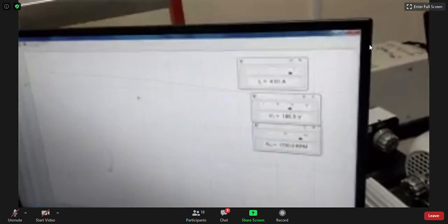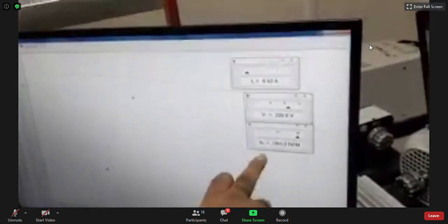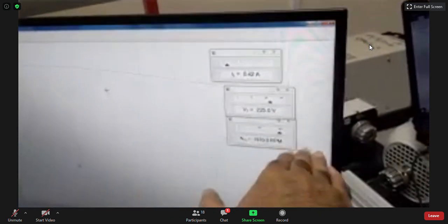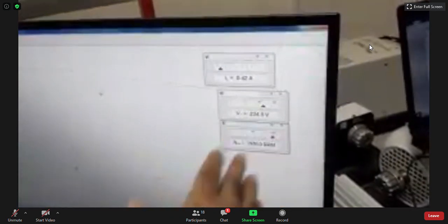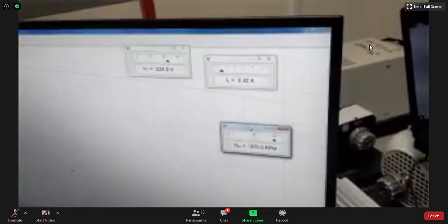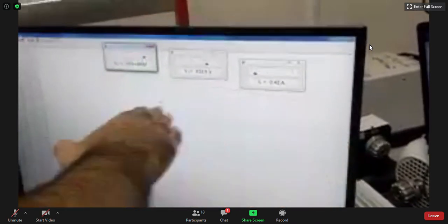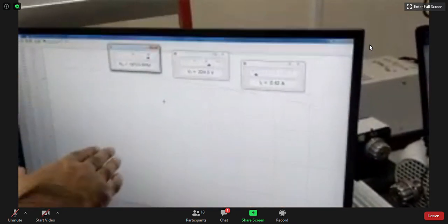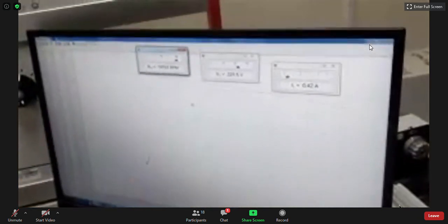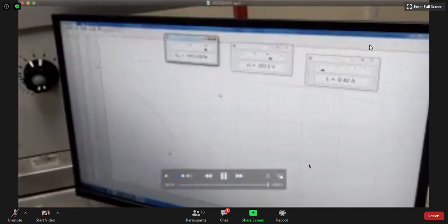So we went until 4.8 amperes. The speed here was decreasing. Practically we should maintain the speed constant, but it was decreasing a little bit, but that's fine. That's okay for our test. Can you see? This is cumulative, this is shunt. For the shunt the voltage will collapse faster than the cumulative, because in the cumulative, as we increase the load current, we have more field current.